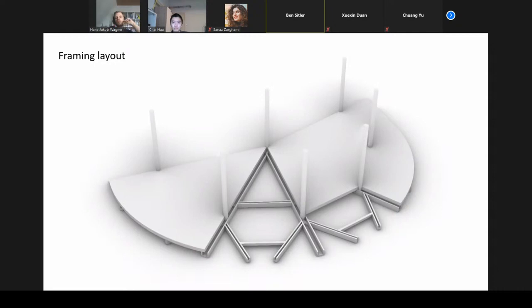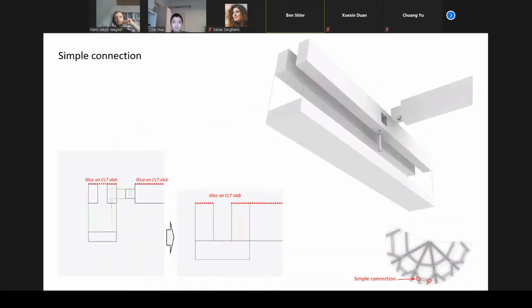connecting everything from below. So the joints that we're thinking are lots of dowel connections where the members basically slot in, we place the dowel, and then we glue the bottom flanges of the beams from below so the dowels become hidden. That takes advantage of building the beam up on site, and it helps create an integrated two-way grid through the structure.